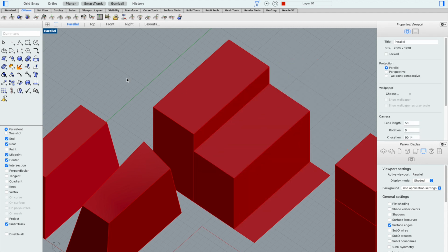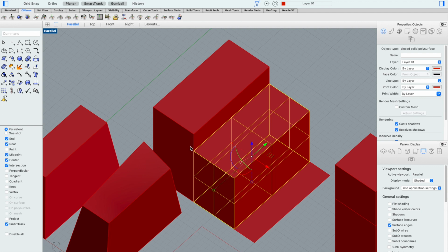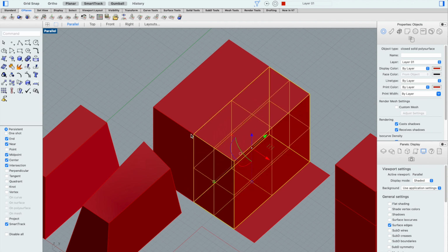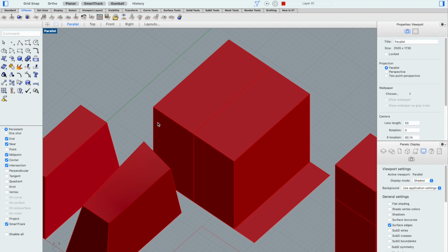If I just wanted to increase the height, then I can use the command scale 1D. Select the base point, select the first reference point, tell it where I want it to end. Done. A lot about how to make stuff and about how to move stuff. Everything that we've made so far, though, with the exception of the hollow areas in the revolve and the extrude commands, were solids. So let's take a second to talk about voids.